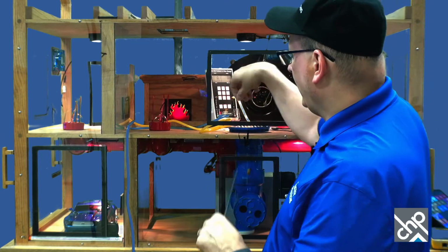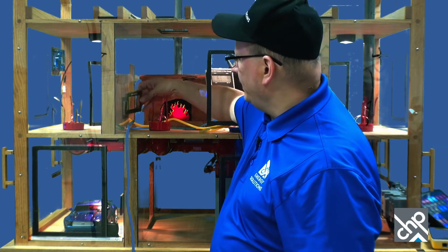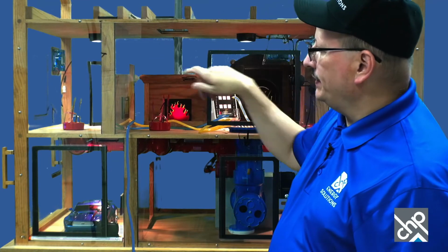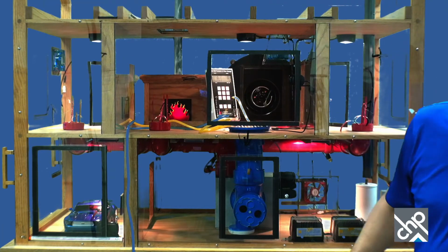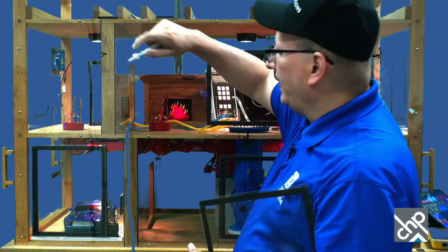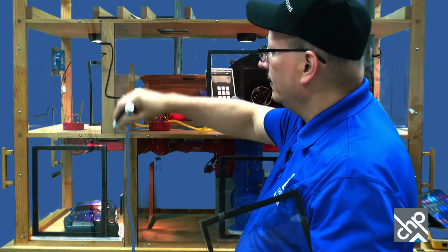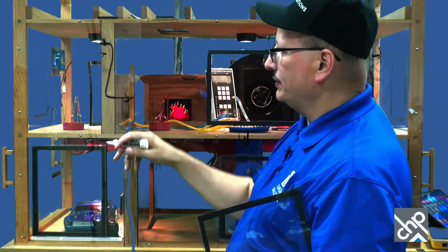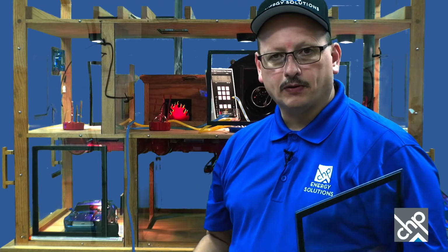And so on my little model here, what I did is I have, you can see it here on this side, what we call a passive return. It's basically a vent in the wall, but I also have a vent in the wall on the other side over here. And what that allows me to do is, when I close the door, it will allow the air to move from this room basically through the wall and then back out into the main body, even when the door is closed. Now, the easiest way to do this is probably just to undercut the door. They have these things called perfect balance. You can look those up online, but they're basically like little grills that go in the bottom of the door.